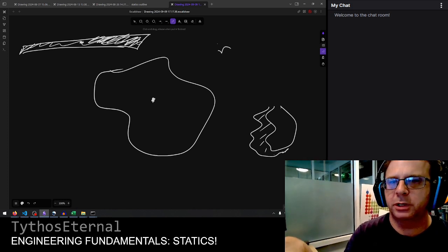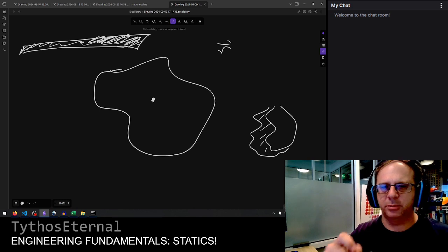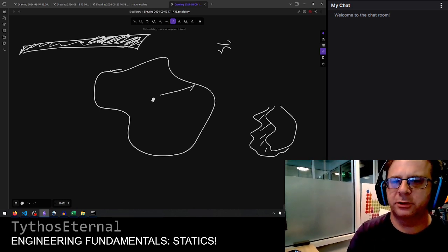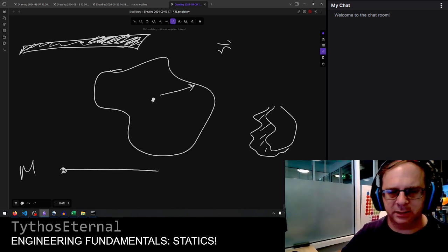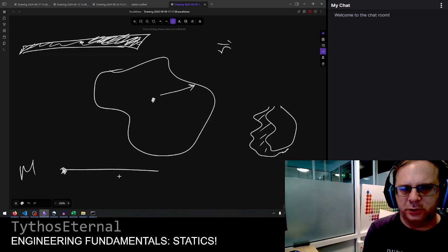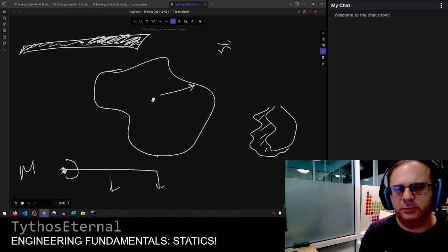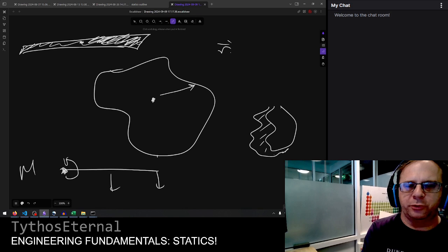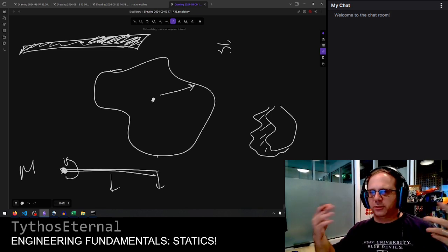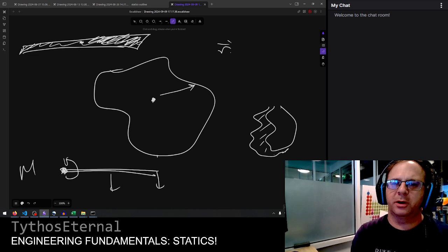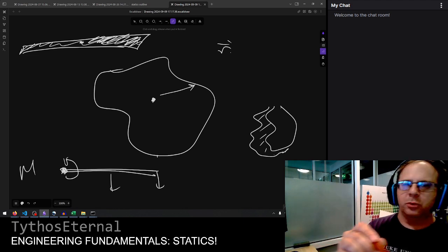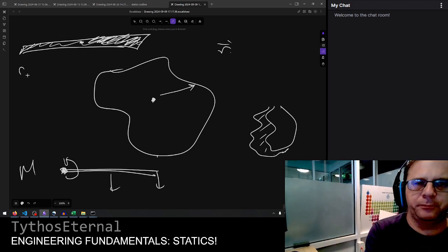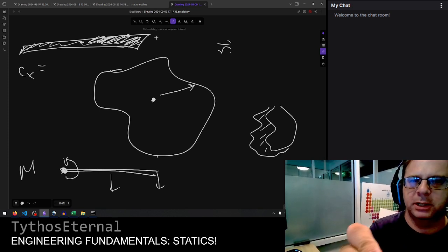Because this R vector here is not just some arbitrary R vector. It can be, but it's typically some relative displacement. When we look at a moment of a beam, for example a cantilever, we're typically going to choose a point and say, okay, there's moments here, there's weight here, there's a person standing on the diving board. So what's the moment that it's completing, right? This R is with respect to some point. And so for given geometries, we need to know what the centroid of those geometries is, so we have a convenient place to determine the moments of.